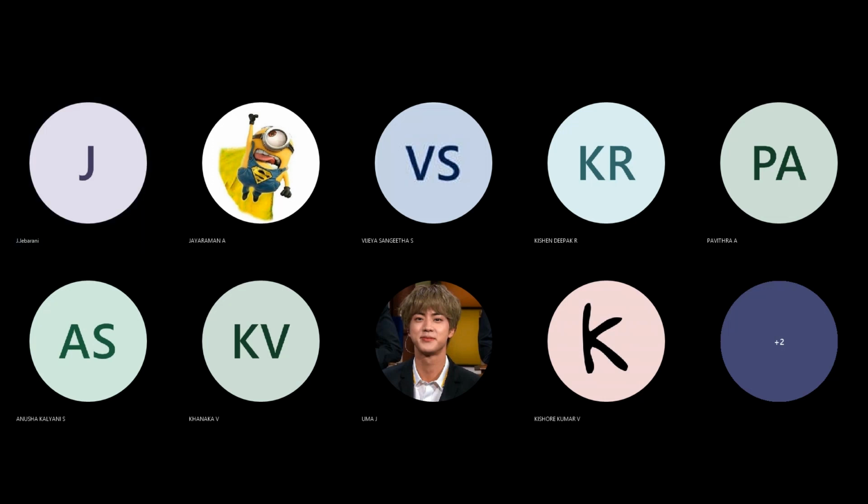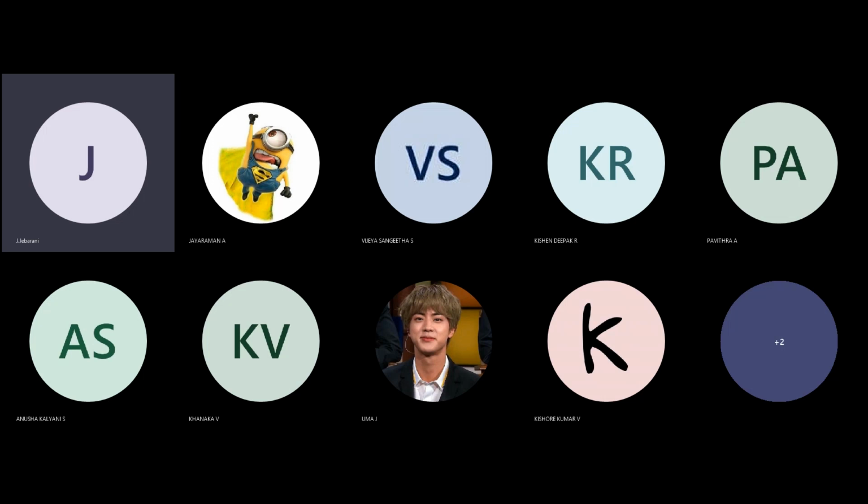So in the other differences between gas and water injection, gas can branch into smaller flow streams inside the part, creating an undesirable fingering effect and unpredictability of gas behavior. It makes it very difficult to control the wall thickness of the part. But when we use water instead of gas to make the polymer product, with the help of water you can easily control the flow.